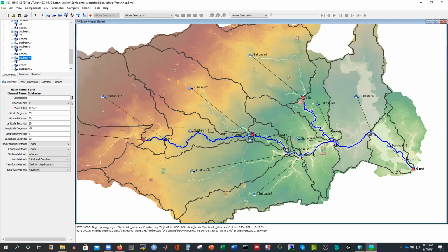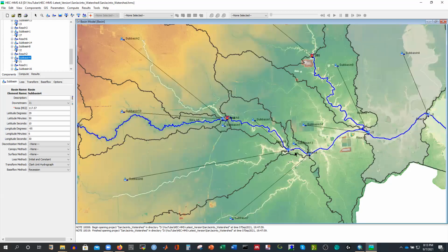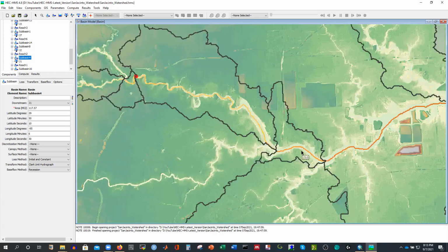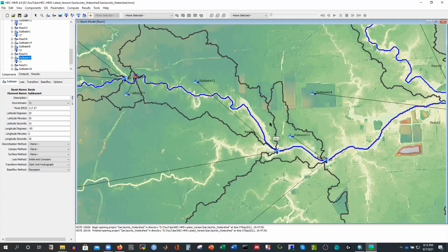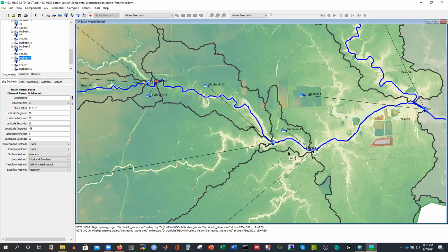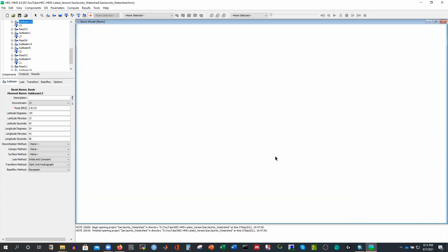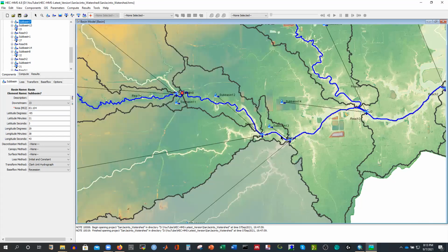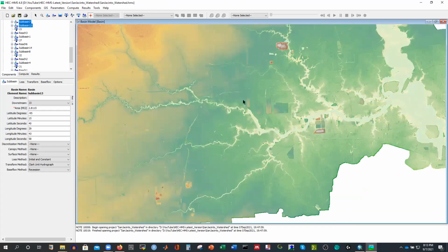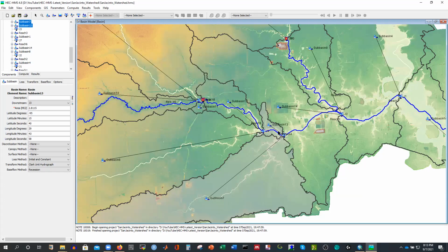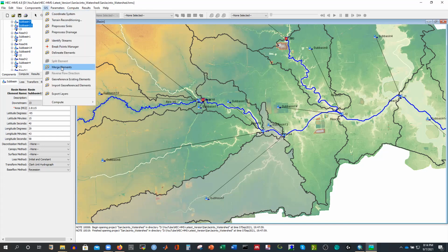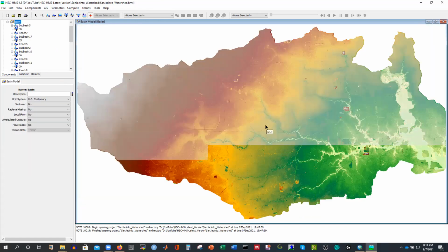So we have only a smaller watershed here. If it is not possible, we can even leave it there, or okay, we have one option. See, that is the option. You have to zoom in and out. So this one and that one, these are both draining there, right? So I'm going to select these two together and merge them. Then we have the total amount of water from both of these two, so there won't be any error in the calculation. That's the convenience, and then it will be activated. So now we are done.